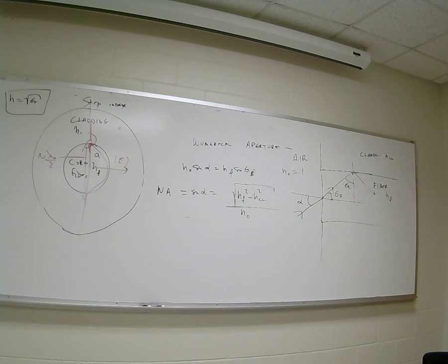Are you with me? Because it's a coherent source. But there's a problem in microelectronics, it's alignment. If you're putting together a system, you want a big numerical aperture, so if there's vibration or a misalignment of the source to the fiber, it'll still couple. Do you all see what I'm talking about?